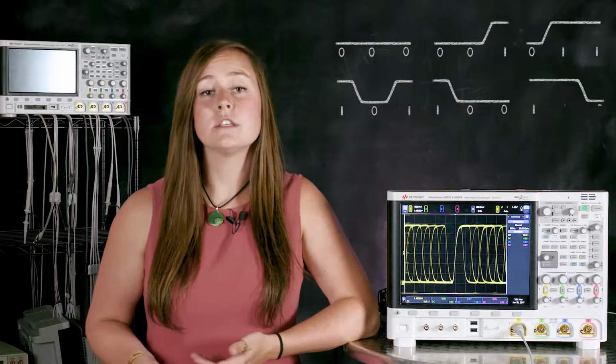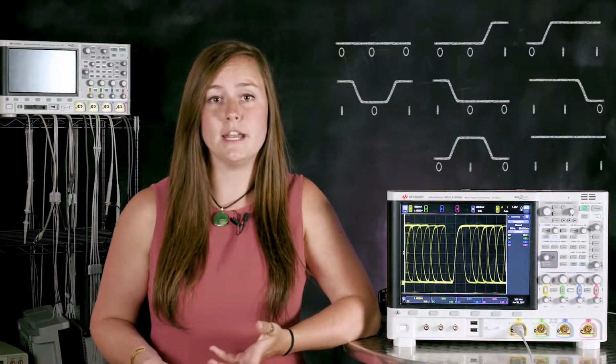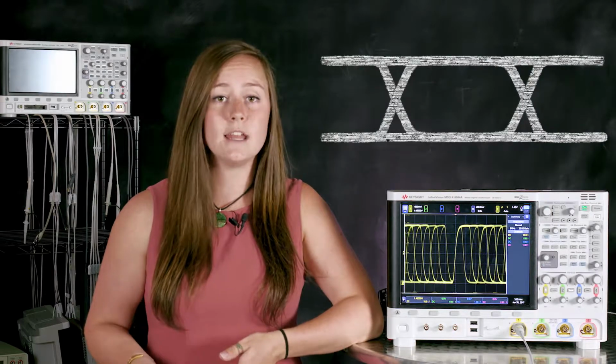Eye diagrams are helpful in testing the physical layer fidelity of clock signals and serial data. So what it is, is a layered view of each of the different bit transition combinations, and there are 8 of those in total. So this provides a composite picture of the overall quality of the physical characteristics, like amplitude variations, timing uncertainties, and infrequent glitches.